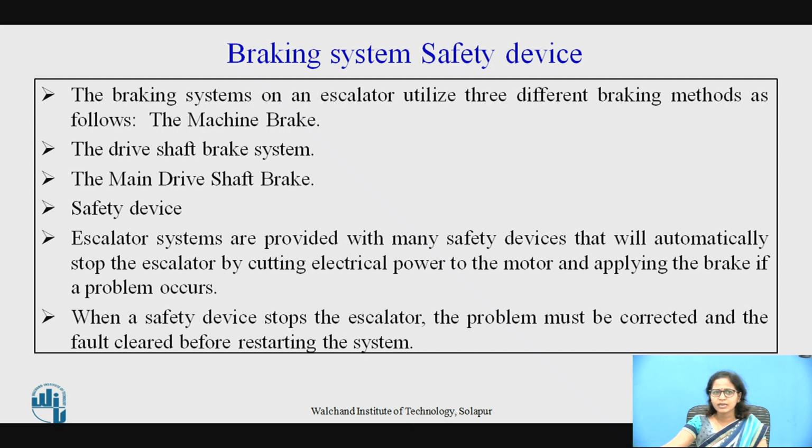Escalator systems are provided with many safety devices that will automatically stop the escalator by cutting electrical power to the motor and applying the brake if a problem occurs. When a safety device stops the escalator, the problem must be corrected and the fault cleared before restarting the system. So these are the braking system and the safety device which have to be taken into consideration.